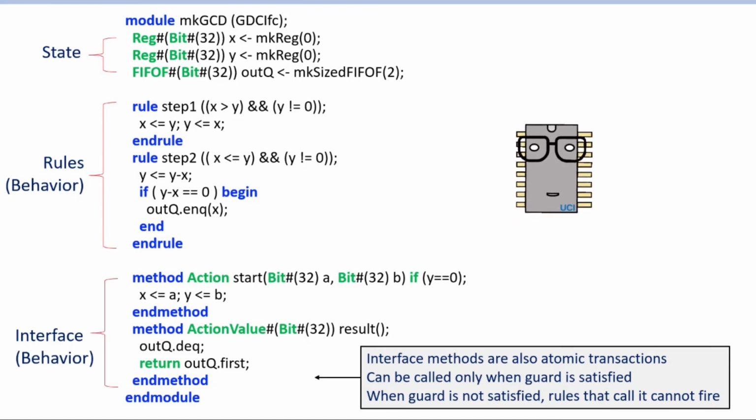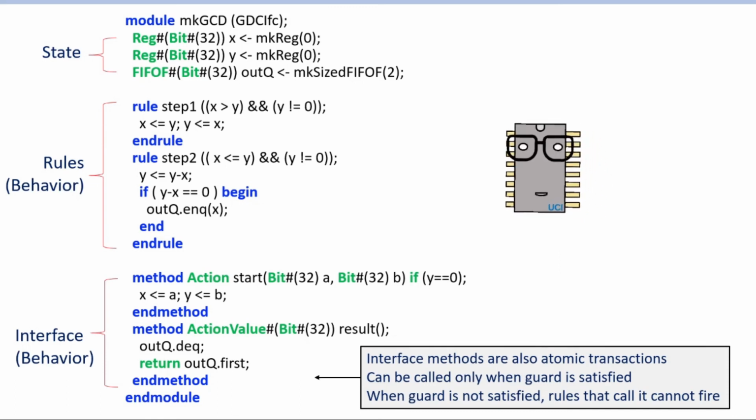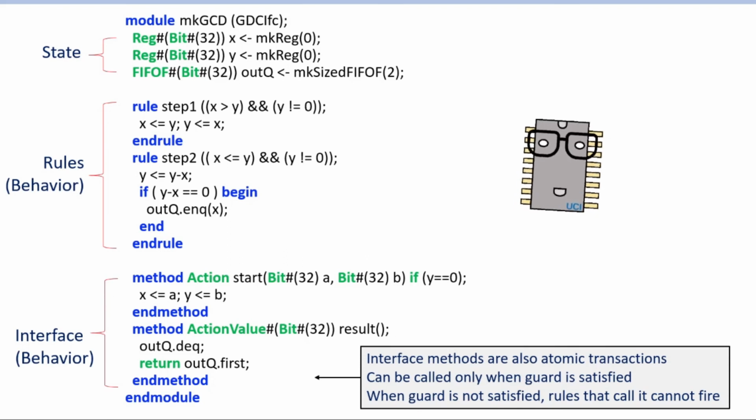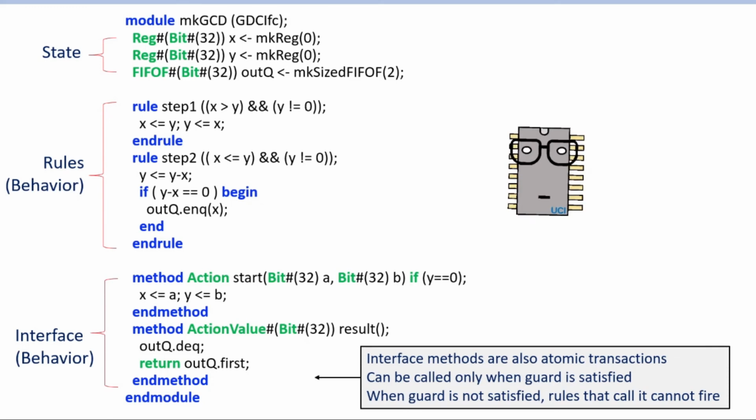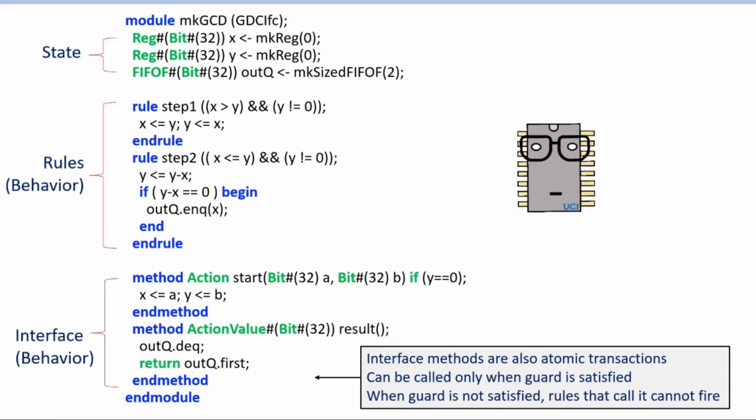I think just because this is pretty much a sequential algorithm, if you were to instantiate one mkGCD in your accelerator, you probably won't get any performance benefits compared to a CPU. Because it is a sequential algorithm, it's pretty much doing the exact same thing your CPU would be doing, maybe.